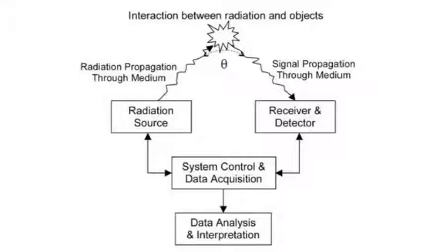For this project, we're using LiDAR, and LiDAR is an example of remote sensing. Another example would be something like radar. Remote sensing is just the method where the thing being collected is not in physical contact with the instrument taking measurements. This LiDAR would be an example of an active LiDAR sensor. Active is when the LiDAR sensor itself has to emit the radiation, the laser beam, in order to collect data. And passive would be when the natural light that's given off is what the camera sees for the data collection. LiDAR is when we use light and bounce light off objects to get a sense of what the objects look like.